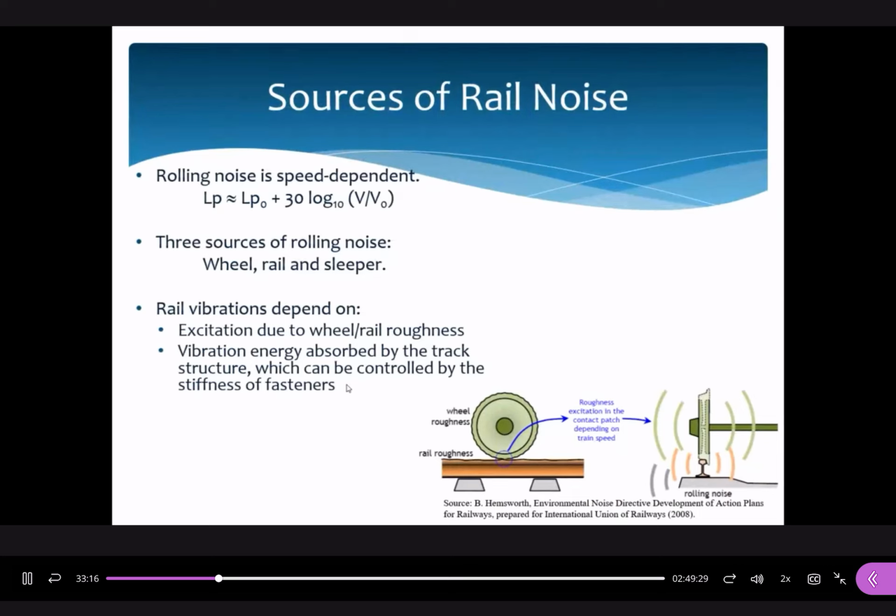This is a general figure to show the rails. This is an I-shape configuration. You can see why we use this one, not a rectangular shape. Do you know why? In the current situation, all the rails are in this I-shape, not in rectangular shape. This is relevant to a structural problem. Even in our buildings, we use I-beams or H-beams for construction. They are relevant to the cost effects, because if you use rectangular shapes, more materials should be used. But when we optimize the structure like this, you can reduce the material use and also provide sufficient support to the dynamic loads above.